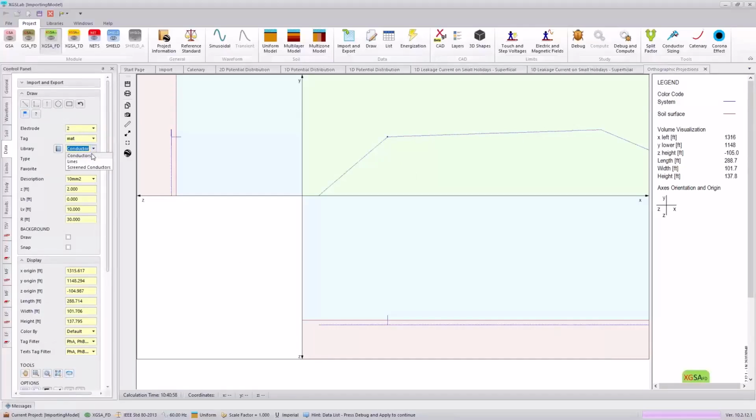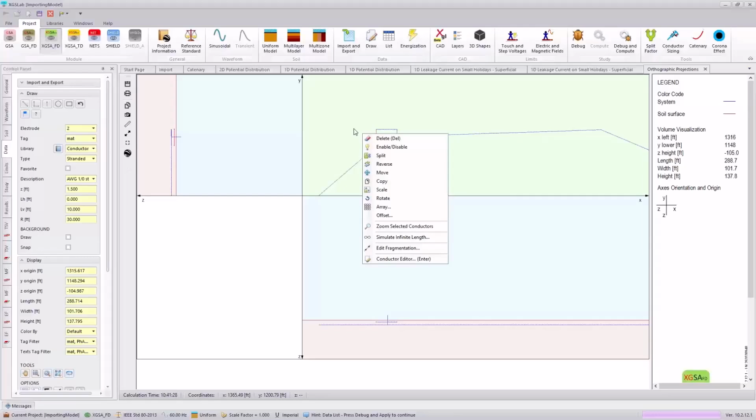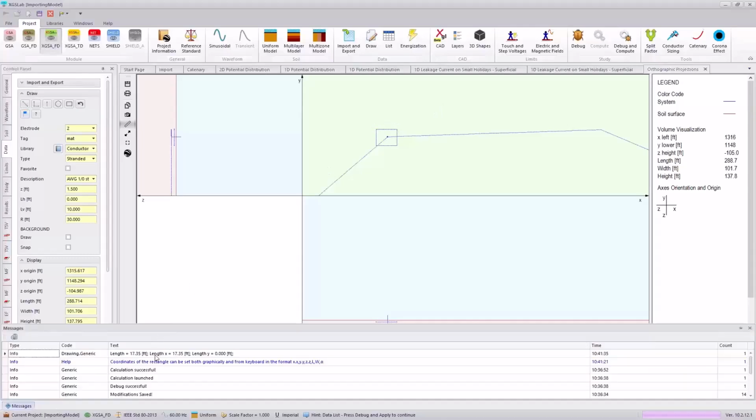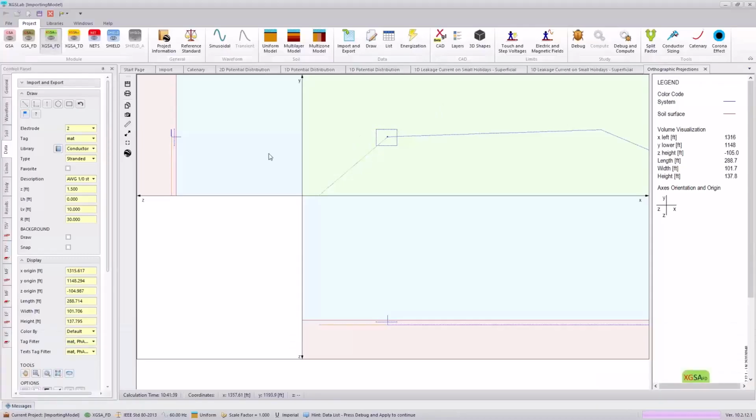It doesn't really matter what conductors I'm selecting right now, we're just going to make a little mesh. So I'll use 1/0, and we can put this at a buried depth of 1.5 feet. And usually I'd be pretty specific as far as how far the mat extends from the test station, but here I just want to make a quick illustration of one methodology to mitigate these systems. So this is about 17 feet long, so we'll make a short array